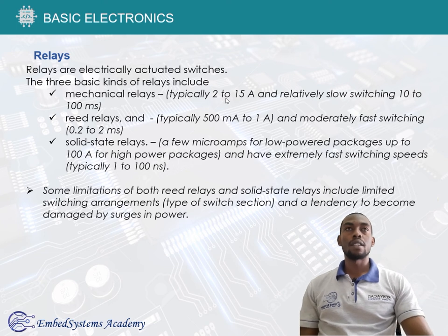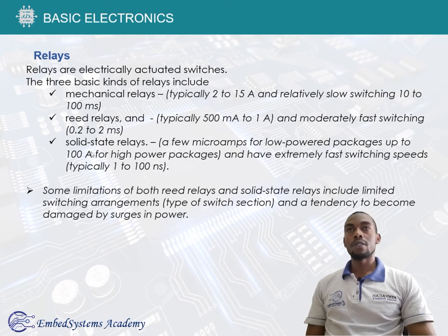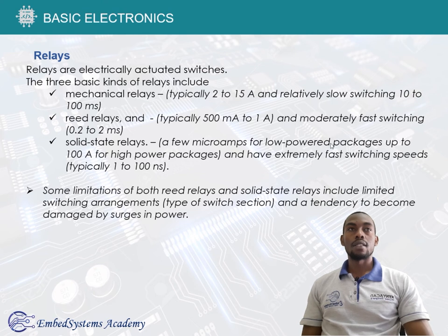Mechanical relays typically are able to switch circuits handling from 2 to 15 amperes, and reed relays can typically handle from 500 milliamperes to 1 ampere. So they are just for smaller circuits, and they are moderately faster than mechanical relays. And then we have solid state relays. These are able to control circuits from a few microamperes to low powered packages up to 100 amperes.